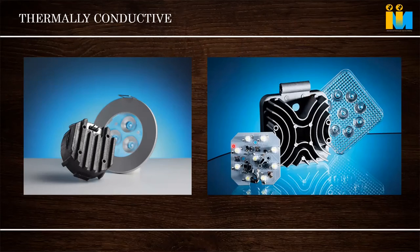Majorly these are used in LED, small LED applications, because earlier people used aluminum heat sinks. Now, to have a lot of fancy shapes and design freedom, people are going with conductive plastic. But whatever the reason, conductive plastics are not as conductive as aluminum. Then how can we do the design? Design plays an important role here, the product design. We cannot just copy the same profile or features of the aluminum to this plastic, because if aluminum has a certain conductivity, this will have only 20 or 25% of that conductivity.